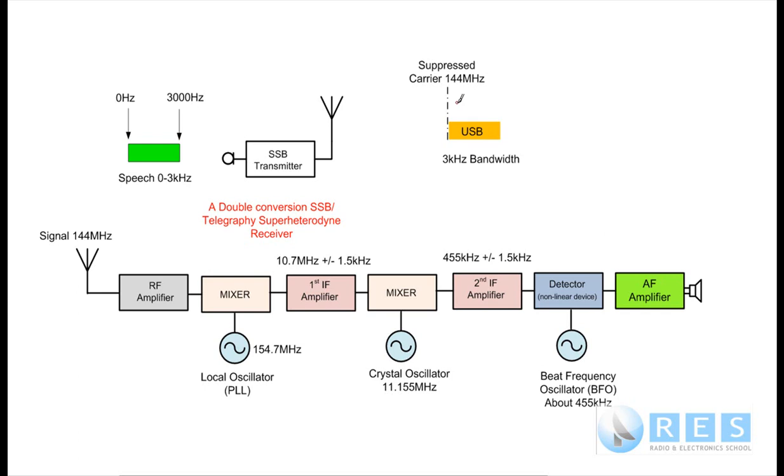The problem with demodulating an SSB signal that we didn't have with a double sideband signal is that with a double sideband signal the carrier was transmitted. So when we fed the sidebands and the carrier into the demodulator or detector, the carrier was there already to mix with one of the sidebands to produce audio output, to reproduce our original audio. With single sideband, we have to have an oscillator reintroduce the carrier.